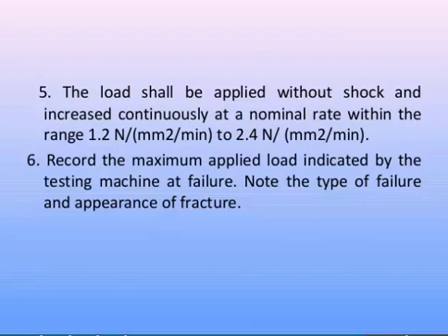Record the maximum applied load indicated by the testing machine at failure, and note the type of failure and appearance of the fracture. We have to note down the failure load, the maximum load which the concrete specimen has taken, which is the breaking load.